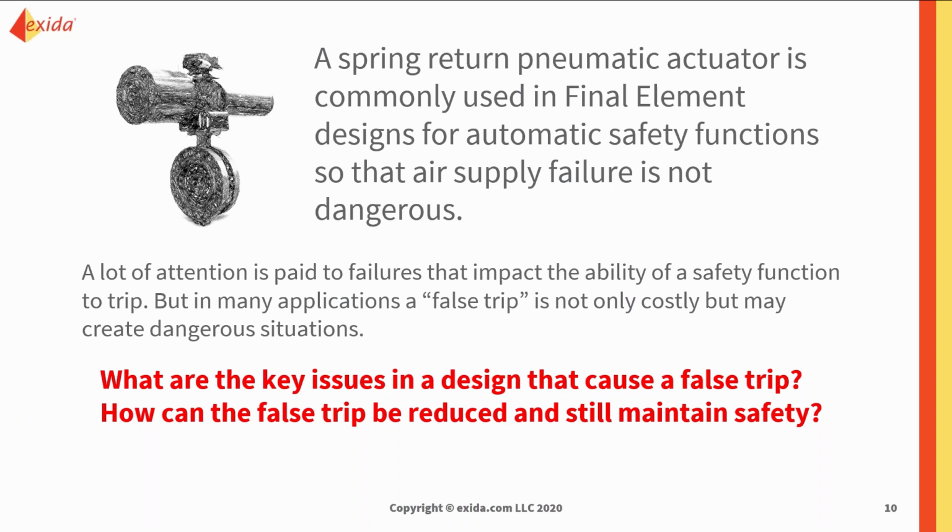And sometimes safe failures are kind of forgotten about or pushed to the side or swept under the rug. As long as you're calculating your dangerous failure rate, that's the priority. That's what you need to know, right? Well, yes, but we also want you to think of those safe failures, those false trips, because those aren't necessarily good things to have either.